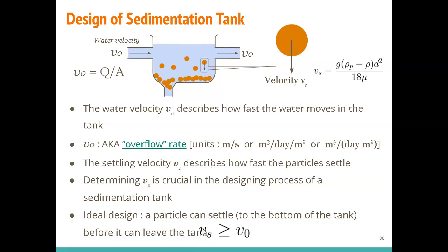I'm sorry about this. So your settling velocity should be larger than or equal to the overflow rate. This is the requirement when you want to design your settling tank.